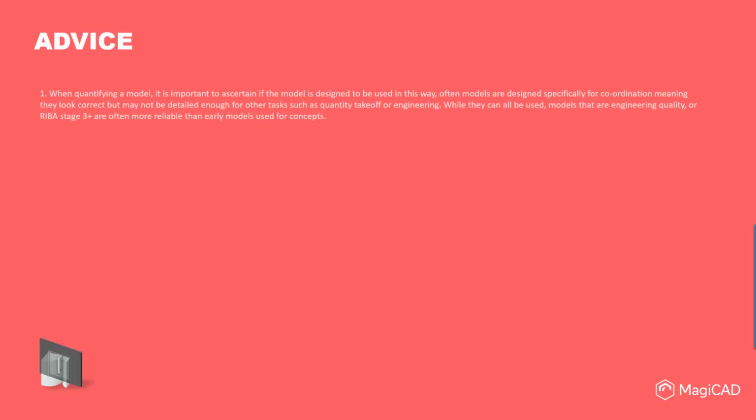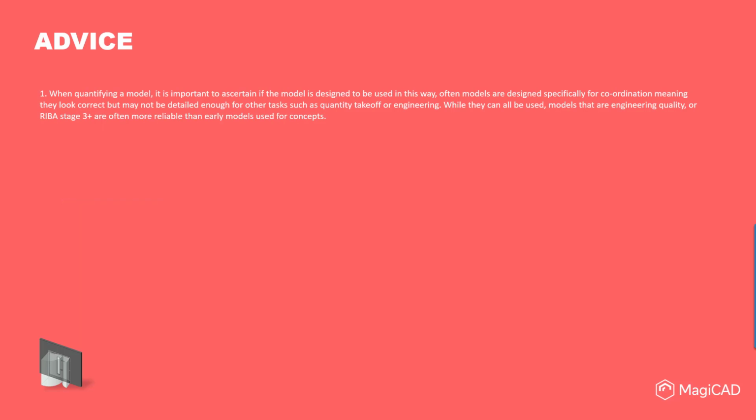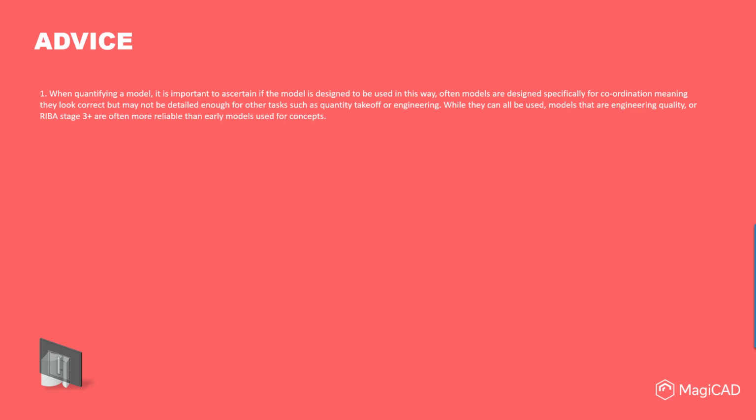Onto the advice. When quantifying a model, it is important to ascertain if the model is designed to be used in this way. Often, models are designed specifically for coordination, meaning they look correct, but may not be detailed enough for other tasks, such as quantity takeoff or engineering. While they can all be used, models that are engineering quality or RIBA Stage 3 plus are often more reliable than early models used for concept.